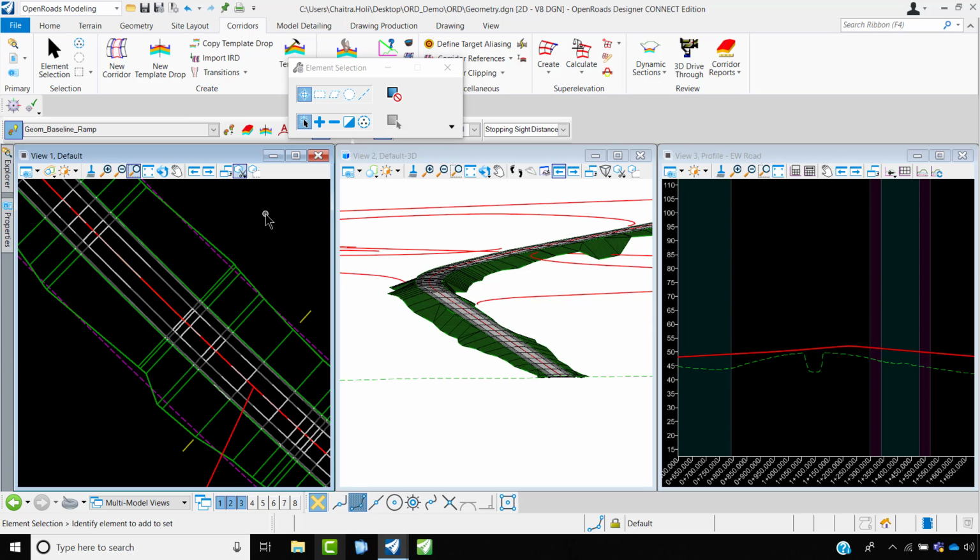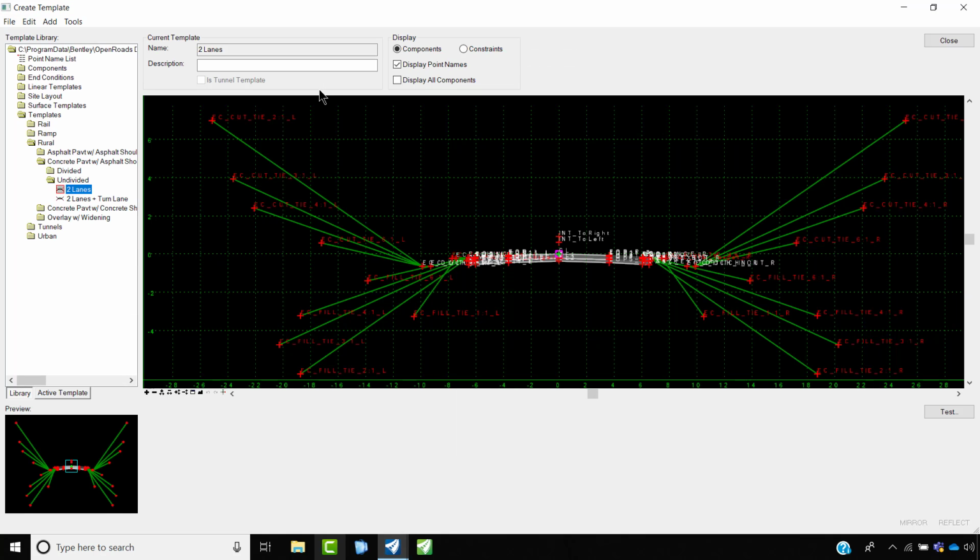So now you would want to know where exactly these templates are present and how I could review those templates. For that, under this Corridor tab, under Create category, you have a template box where you'll choose Create Template. This will take me into a separate template window, where you see the template file ending in .itl, the civil templates metric .itl file.